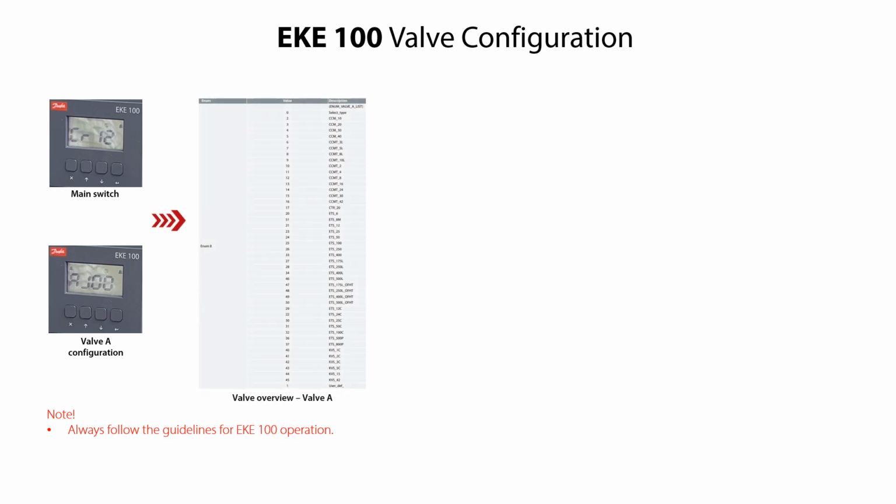You can see the different suitable valves and related values in the overview shown here. Press the arrow up or arrow down keys to find and select the needed valve. Select 29 corresponding to an ETS12C valve. Press the Enter key to confirm the value and return to the AJ00 mode.